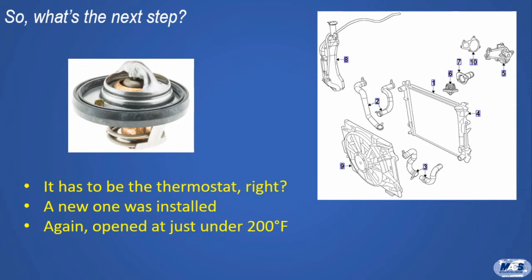If the coolant temperature at the thermostat housing had been changing in accordance with the problem he had, that wouldn't be the worst thing he could do. But the temperature at the housing outlet was consistent with the thermostat opening at just under 200 degrees Fahrenheit every time. A new stat wasn't likely to do anything, and we'll reassure you by admitting it didn't.